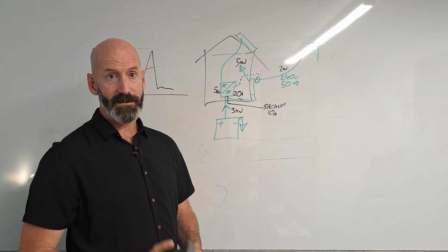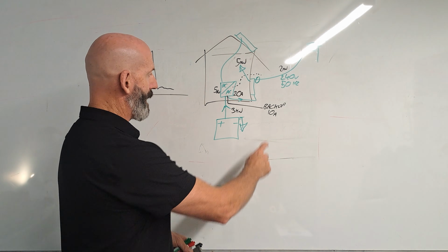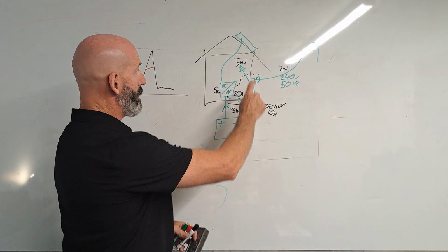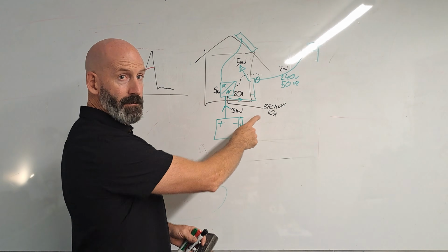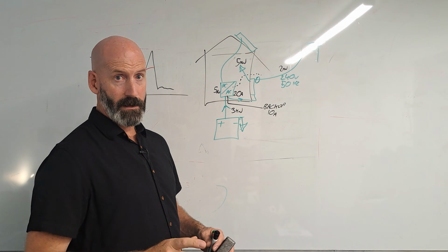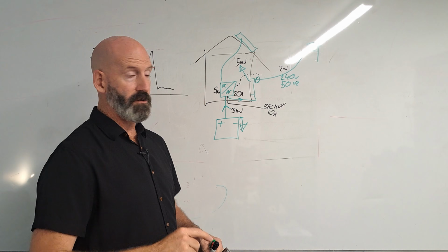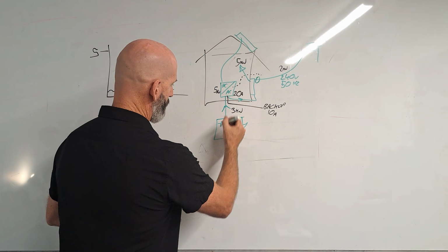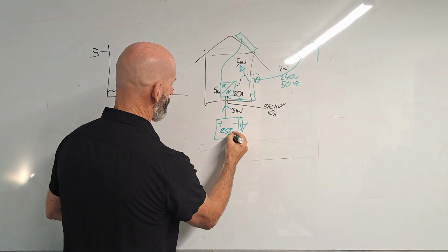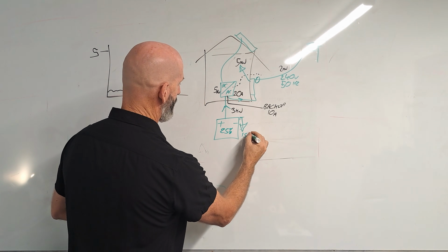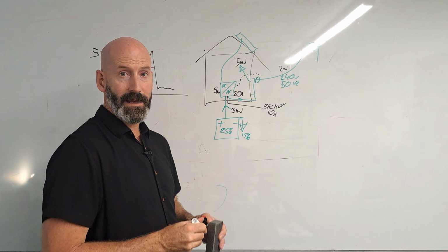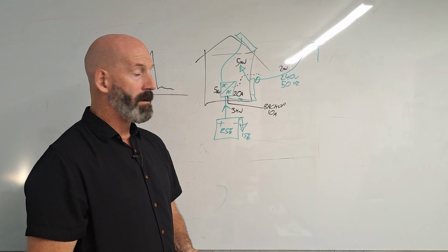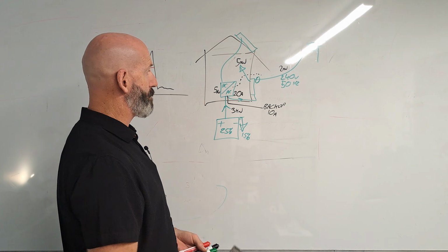They're not designed to be disconnected from the grid for long periods of time, and they generally have a limited backup power supply. Another thing that you'll find with a lot of hybrid systems, once they're in backup mode, yes, you've got limited power, but a lot of them won't actually produce directly off the solar panel and create a full standalone system. They will only give you whatever is left in your battery. So at the time that the grid goes down, your battery is at 25%, and you cut off, let's say, at 15%, you only have 10% of your battery before you're completely out of power, and your hybrid system is not going to produce because it is only designed to work in this backup mode.